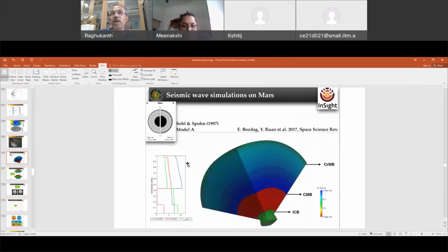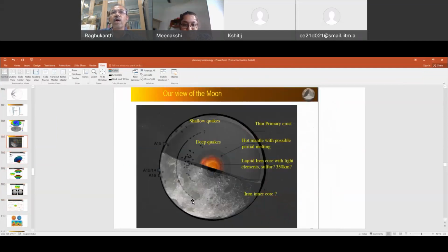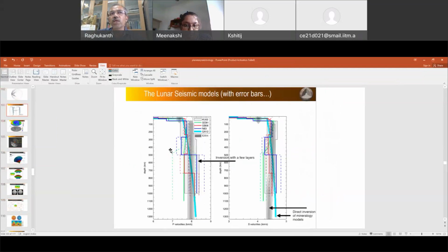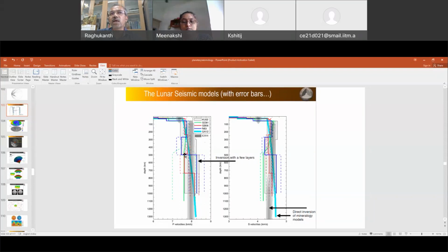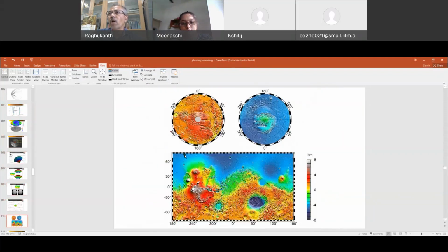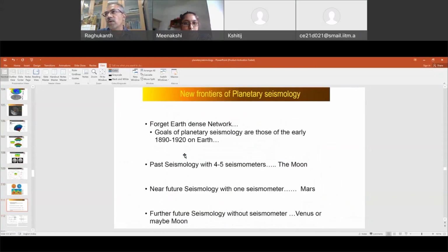So the velocity model is available, and everything remains the same in Mineos. Only the Earth velocity model, the preliminary reference Earth model, changes. Similarly for Mars, we will use this velocity model, and for the Moon we also have a velocity model. So you take one here, one Earth, simulate the default earthquake, and get me the time histories. You can even plot the natural frequency of all the modes, the spheroidal modes and the toroidal modes, and then observe the differences between those 3 planets and make some conclusions.